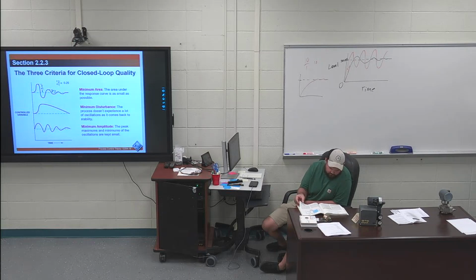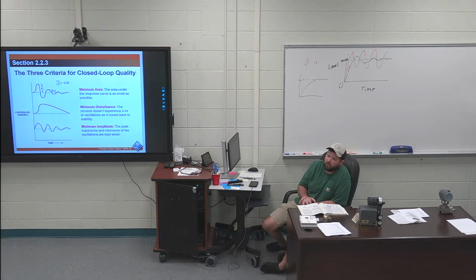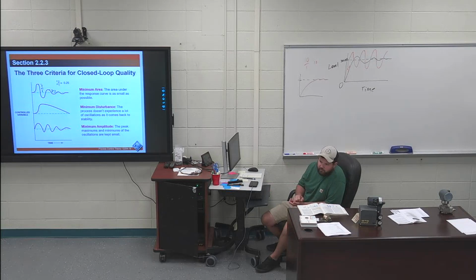Page 22 and 23. And all of these are just adding more and more control. So you started with feed forward, or open loop control. That has no control essentially. You're just doing the control. Feedback, you're using one control loop. Cascade control, you're using 2 different control loops to make a more fine point adjustment in your process.